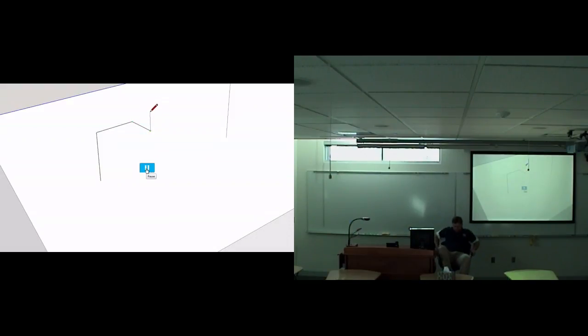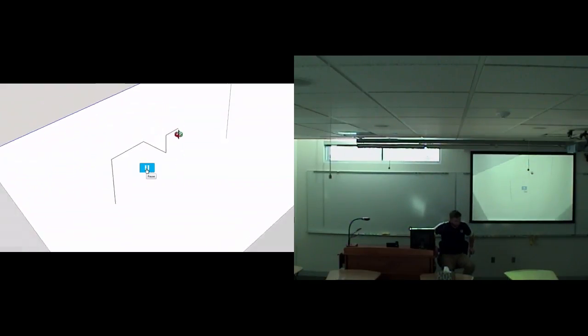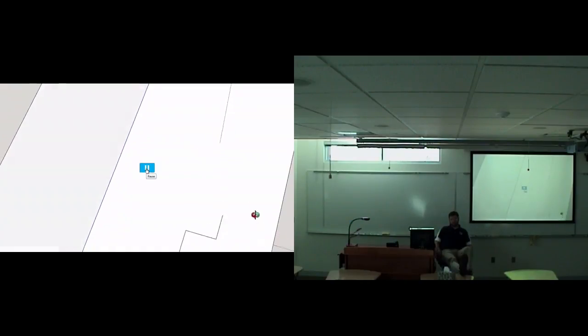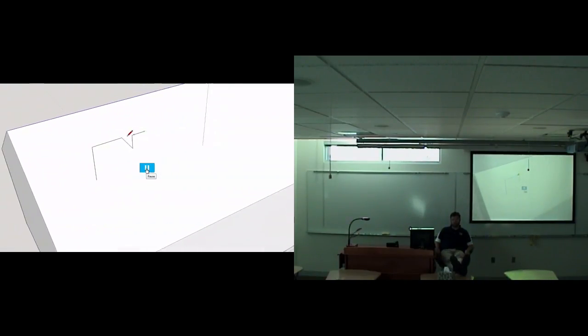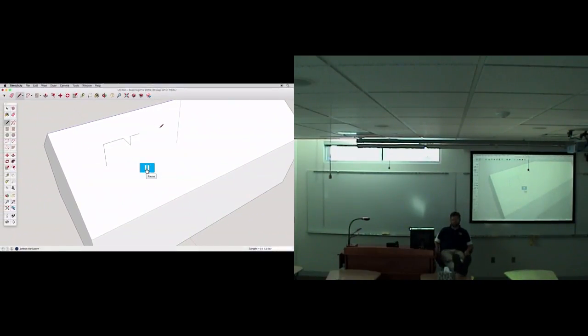Around to see the orientation. The blue direction is vertical, straight up and down, and the red and green are horizontal. To draw a chimney, we could approach it in many ways, but we'll use this method. We'll draw the side profile shape, then use push-pull to create the full chimney. Drawing with the axis directions will help us create the correct profile in 3D space.